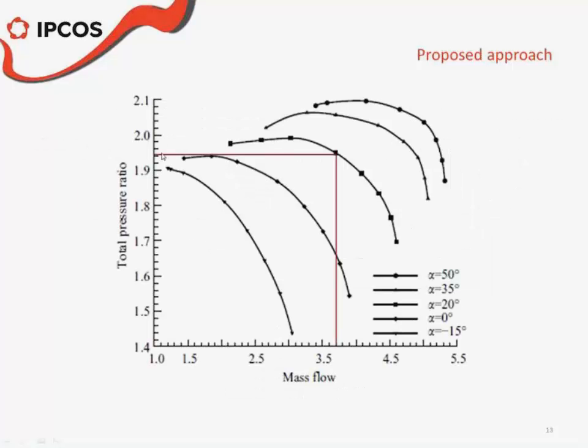Not only that, you will be working all the time probably at the same point in the performance curve of the compressor, avoiding coming close to surge and keeping the efficiency of the equipment more constant.